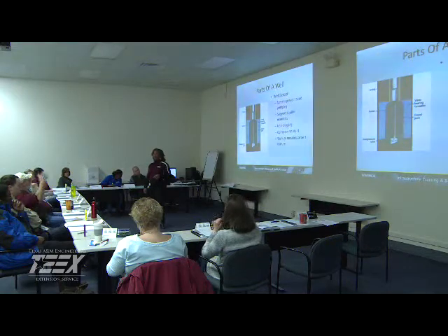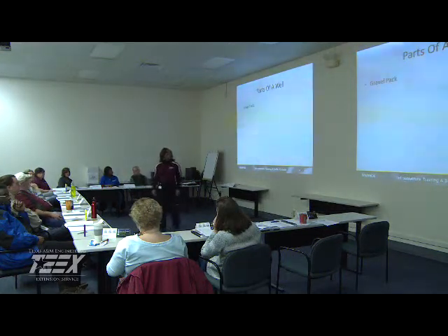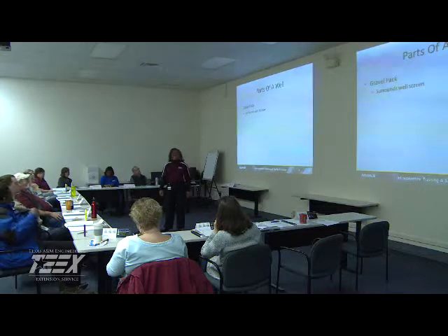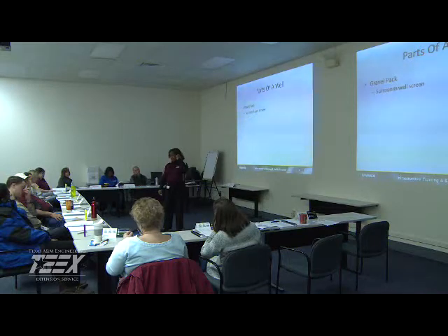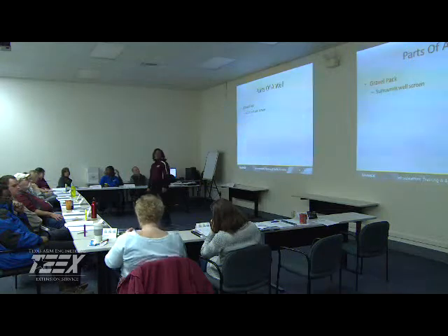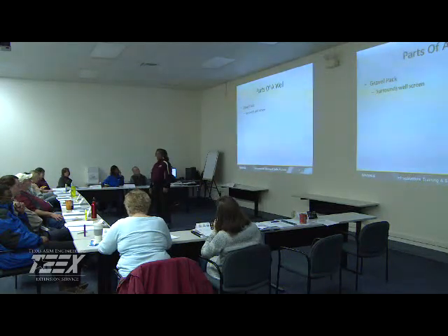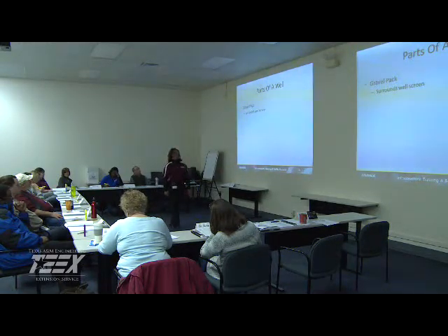Okay. Because some put in 2 screens, connect 2 aquifers for irrigation wells. So there could be a cross connection in the ground. Two aquifers and you screen from both at the same time? Yeah, well, I haven't read the whole thing, but from the drillers, it's a fairly common practice if you don't get enough water in your first aquifer, just to keep going to the next one and screen both, but the regulating agency doesn't like that. Didn't like it at all.